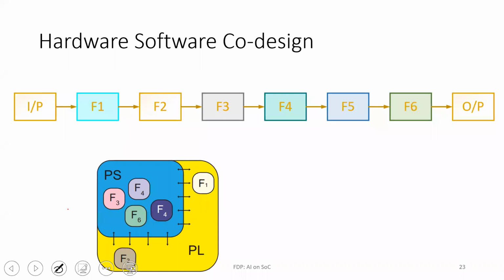For example, sometimes the user has a cost constraint, and in that case, using the FPGA may not make any sense. So you can just say, okay, everything will be implemented inside the PS. I will not use the FPGA. Sometimes the user wants very high speed, like low latency. In that case, you can tell the user that if you use the PL, you can get better performance, but it will be slightly more expensive or have more power consumption.